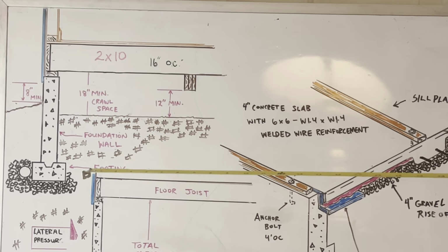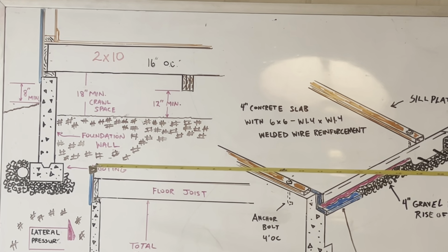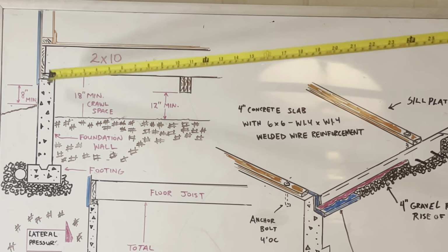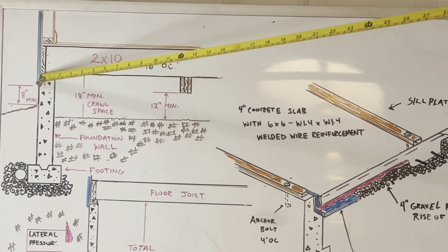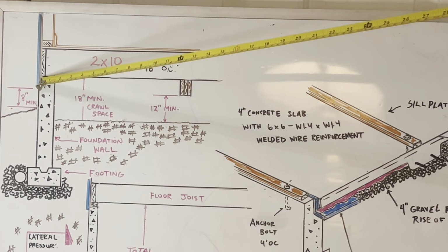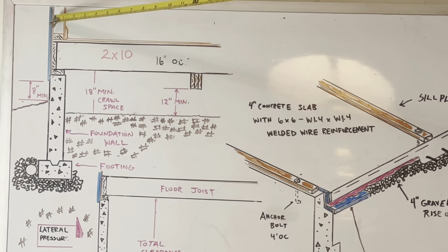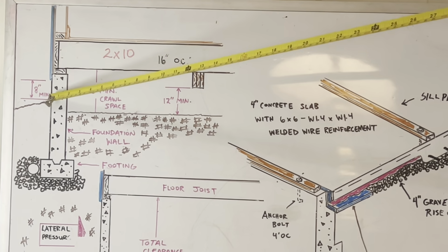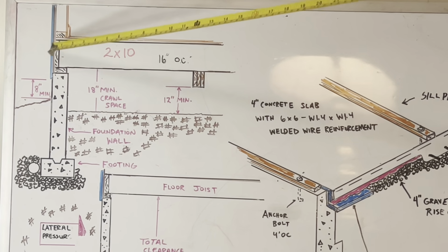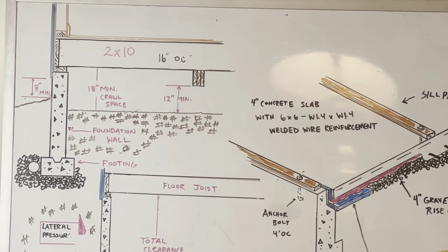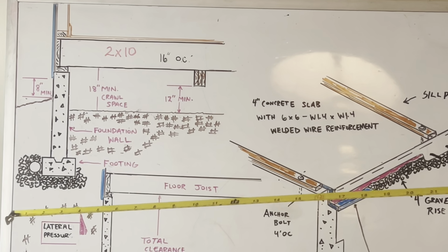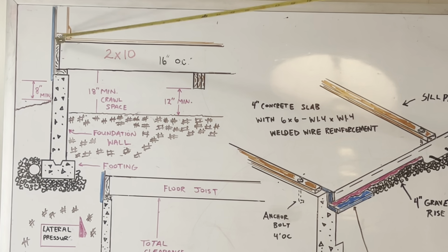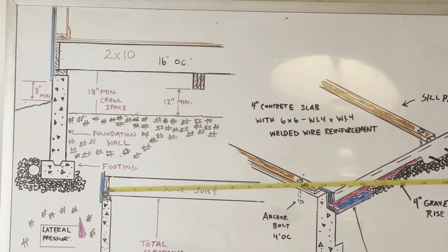If someone is building or you got to come behind someone else's work, hopefully they've done it to code, okay? Now, if you look right here, on the outside, of course, you got your sheathing, okay? Either OSB or plywood, okay? Then next you'll come with your building wrap. I know y'all probably seen it. You've seen somebody doing construction before. They had a Tyvek building wrap a lot of times around the building. And then you'll come with some foam insulation. It's like styrofoam insulation right here.